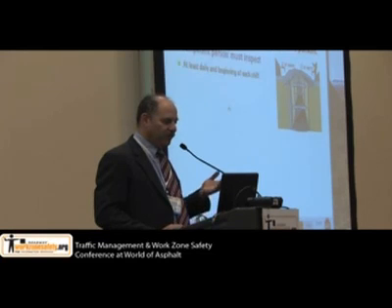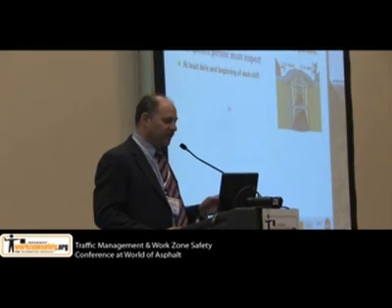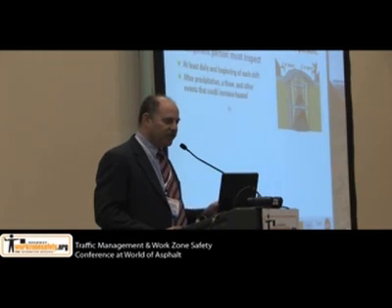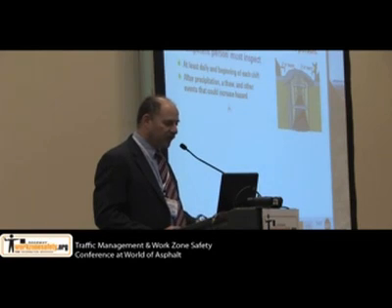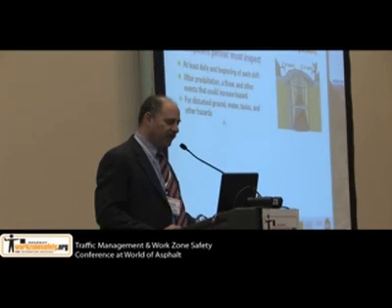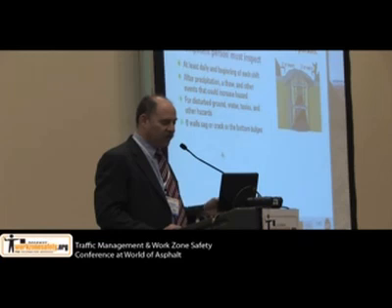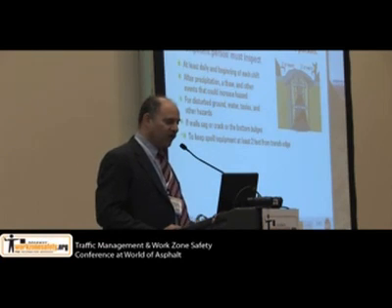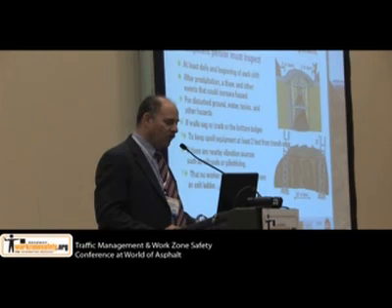And these are the responsibilities of the competent person: to do an inspection at least daily and at the beginning of every shift, after there's been precipitation or a thaw, if they see any disturbed ground, water, toxics, or other hazards, if they see walls sagging or cracking or bulging, to keep equipment or the spoils pile at least 2 feet away from the trench edge, check for any vibration sources, and make sure that no worker is more than 25 feet from an exit ladder.